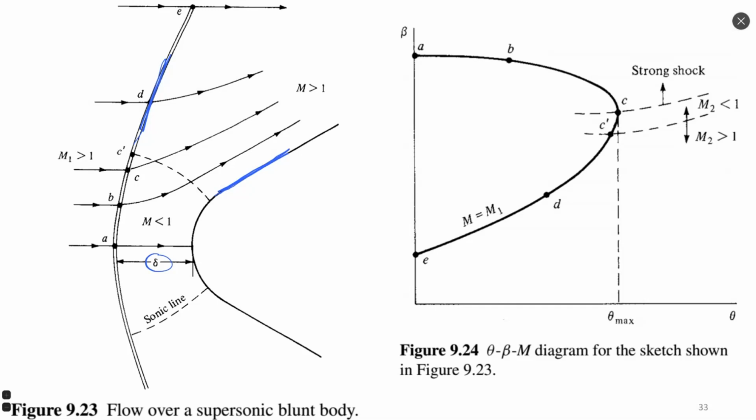Yeah. Also keep in mind that it's a blunt body, not a planar body. It's an axisymmetric body, so flow lines are curved. They are not straight lines after the shock wave. So such a structure can be calculated in the simplest possible way as a solution of ordinary differential equations, not as a simple algebraic model. Even properties on a shock wave cannot be calculated by a simple analytical or algebraic model. It should be a solution of differential equations. But I think it's a very interesting question. If someone would like to study more, it would be a possibility.